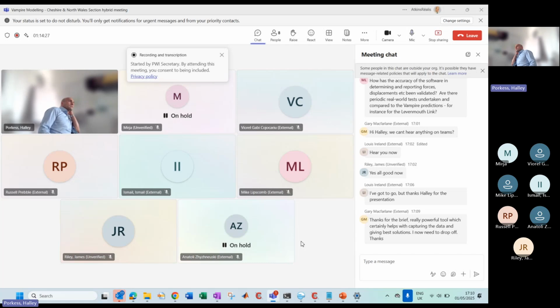Is that just wheel-rail interface as well? Not looking at gauging yet. Vampire. For gauging, if I say the term absolute gauging, do you know what I mean? Using Curie. Yeah, so the vehicle models which are used in Curie, you've got different types of vehicle models, but the most accurate model is created essentially using a load of lookup tables that come out of Vampire. So you have a vehicle model and you run a number of cases to predict how much the vehicle is going to move. That produces a load of lookup tables, which are then used in Curie.